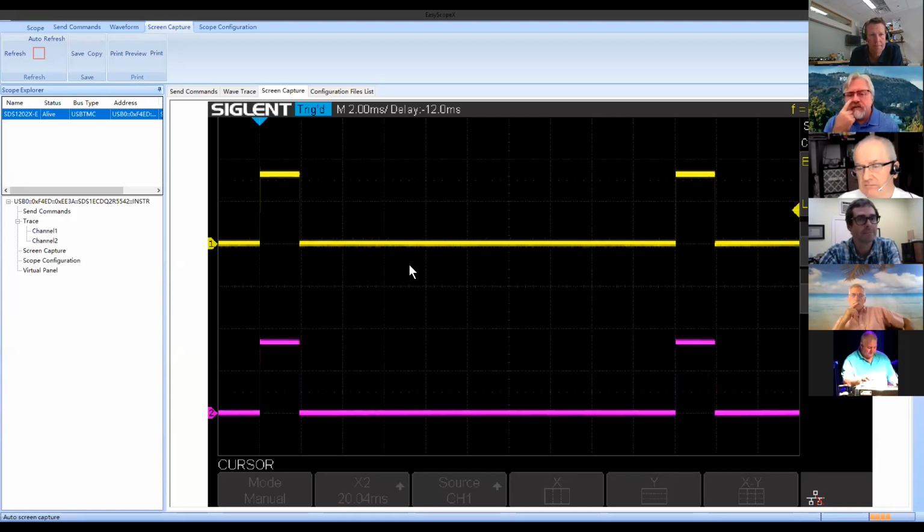What the smart pins allow, and I might ask for an assist here, Chip, is that you can put an offset into them to pre-start them so that you could create a cascade effect. In my P1 servo controller, which gets used a lot, I only run one servo at a time. I output a pulse. So here, for those that, this is the servo pulse. Here's the next pulse 20 milliseconds later. In my servo driver for the P1, I run the first channel pulse, 2.5 milliseconds later I run the next, 2.5 milliseconds. So I do a stair step approach. So only one servo is ever activated at a time.